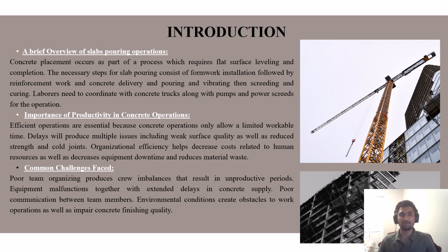Now, when we talk about productivity in these operations, we are really talking about maximizing the efficiency within a narrow window, since concrete has a limited workable time. As it gets delayed, it results in cold joints or weak surfaces which compromise structural integrity. From a management perspective, productivity also means saving labor costs, reducing material waste, and minimizing downtime.